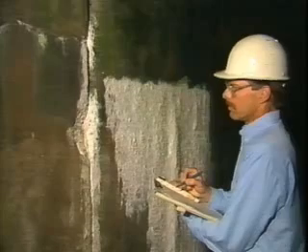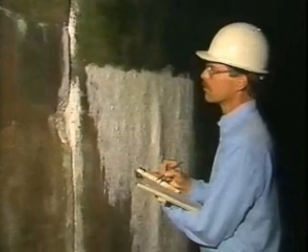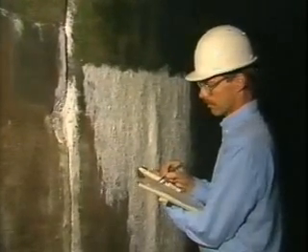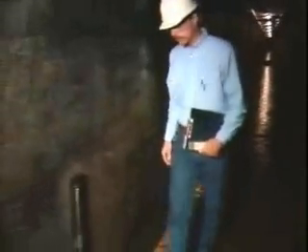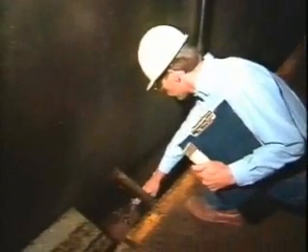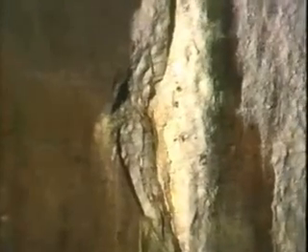Leakage in the interior may occur through cracks and joints extending to the upstream face. Try to determine the rate of leakage and compare your data with previously reported rates for similar reservoir levels. Weirs may be placed in gallery gutters to measure leakage. However, remember that gutters collect flow from the form drains and the foundation drains as well. Also keep in mind that deficiencies found in the interior may indicate conditions on the upstream face that are below the surface of the reservoir.